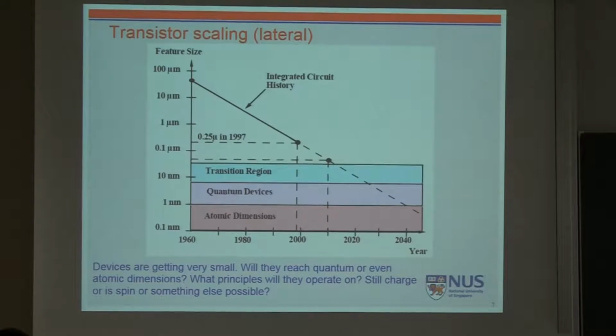However, it is very clear now we have enough transistors. If you talk to Intel people, no need to add any more transistors. A billion is enough. The biggest question is power, because it consumes so much energy because it flips so many times per second, and with interconnects and each transistor, it consumes a lot of charging and discharging energy loss. So this is one of the biggest issues we are facing right now, where spin electronics can play a very important role with low power consumption.